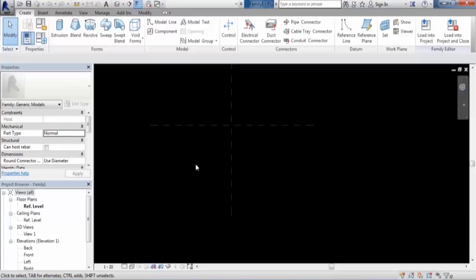Again, if I need 200 by 200 by 300, then you have to make another one, 200 by 200 by 300, different. You have to make that in AutoCAD. But in the Revit, you only make one box, and you give the parameters, length, width, and height. By changing parameters, you can make so many boxes.